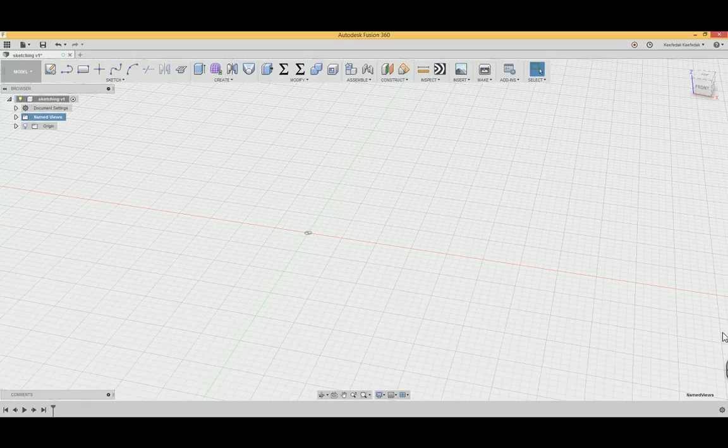Okay, here's the thing that gets people who are beginners. Most of the time, 98% of the time, all functions when you're drawing or doing anything, you will click at a spot. You click, let go, move, and then click again. Whereas in a lot of the programs that people use, they click and hold and drag. We don't do that very often in CAD, okay? That's because when you click, it allows you now to put numbers in or change things in the design. So get used to this whole notion of just clicking, letting go, moving, and clicking again, okay?